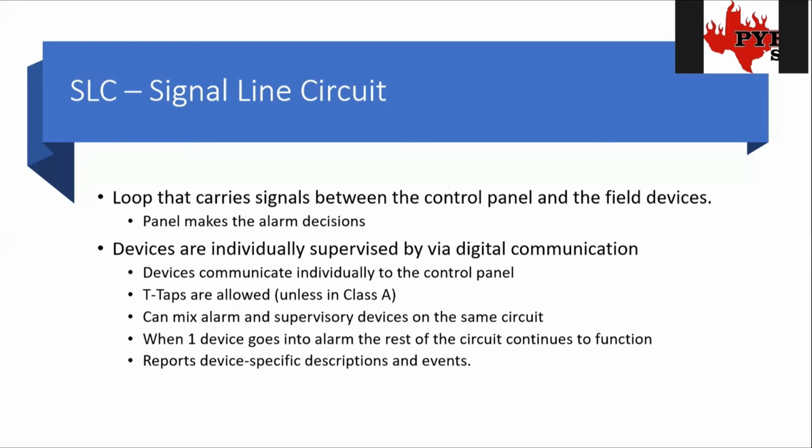Something I forgot to mention with the IDC circuits, because it's the whole circuit that initiates the alarm and the panel can't talk individually to the devices, you can't mix supervisory type devices and alarm type devices on those IDC circuits. So for instance, if you're monitoring a sprinkler system and you got one water flow and one tamper, you have to pull two separate zones over there, one to monitor the tamper since it's a supervisory signal, and one to monitor the alarm, which is the water flow.